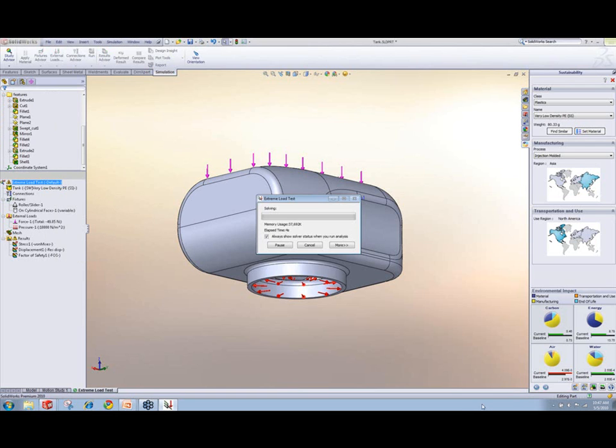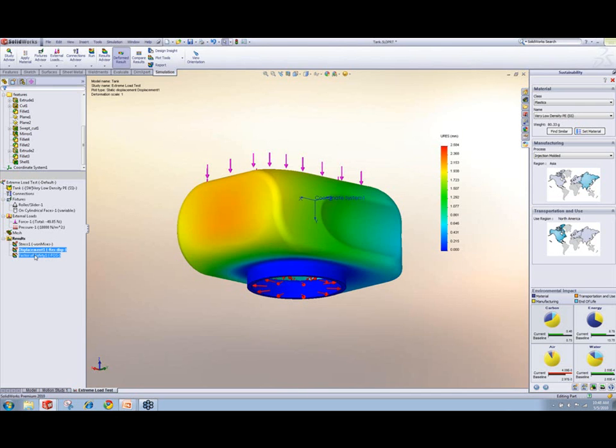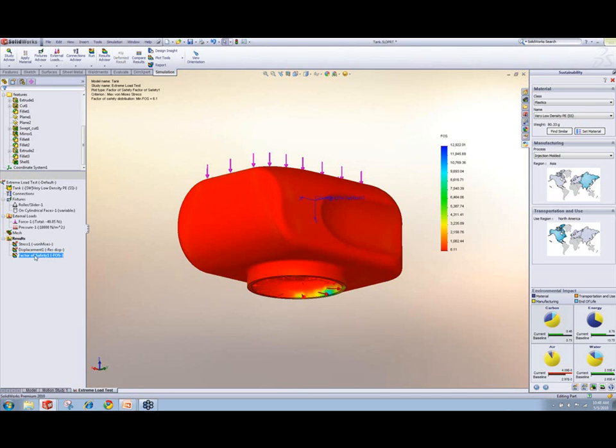Any questions while I'm running the study here? All right, let's continue on. So this is our stress, our displacement plot. We're currently interested in the factor of safety. So we've chosen a new material that's a little more environmentally friendly, and we've only sacrificed about three units of factor of safety, which is not bad, since we're still above our two units of factor of safety. So we've actually still over-engineered the part. There's still much to be done.